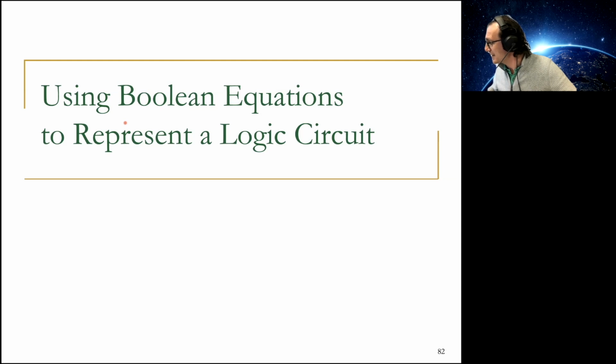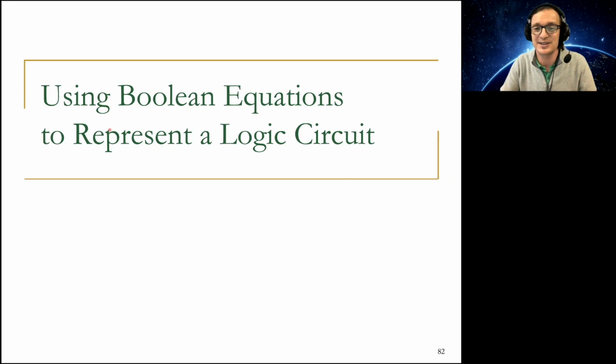So is single event upset affecting transistors? Yeah, there are a lot of issues that affect transistors today, especially if your transistors are vulnerable to noise. Single event upsets mean you get a particle strike, let's say, or for some reason your transistor flips from switching to non-switching, or your output flips from 0 to 1. That could happen because you have a lot of noise. And these things usually happen at more extreme conditions.